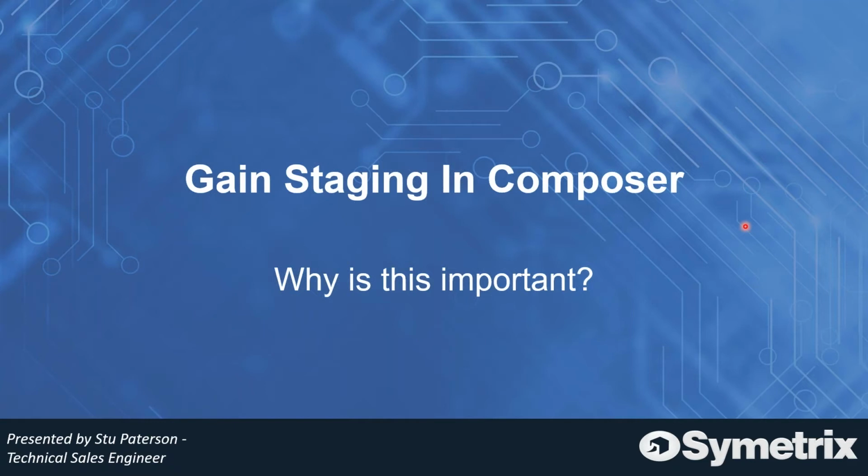And today we're going to be discussing gain staging and how it relates to designing a system around our products. This discussion will be focused entirely on how Composer handles gain structure and how we calibrate our input levels based on the source material, input, middle, and output processing, and finally the outputs, whether that output is an analog output or a Dante TX bus or transmit bus.